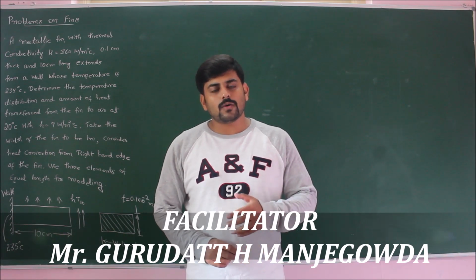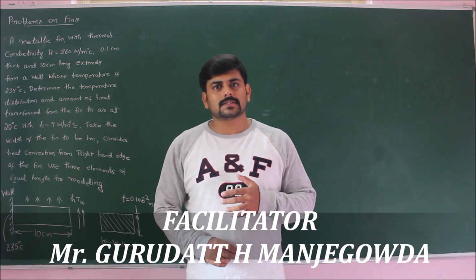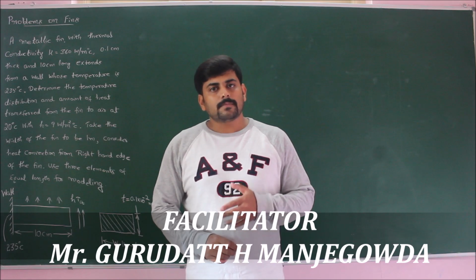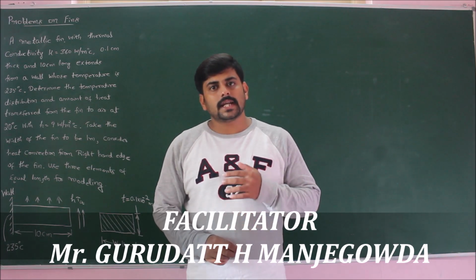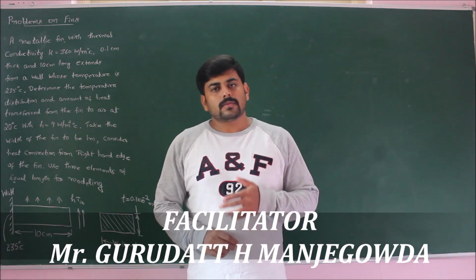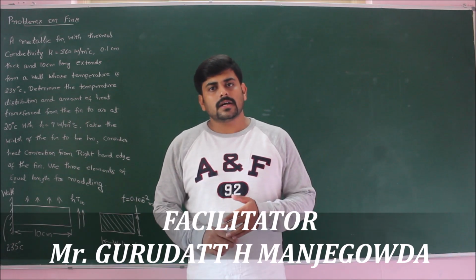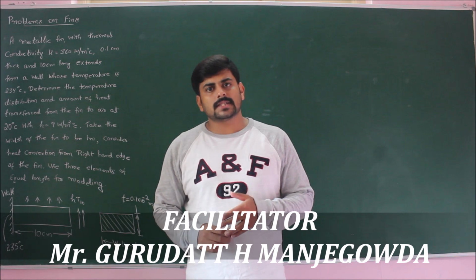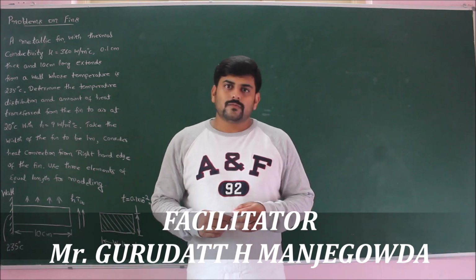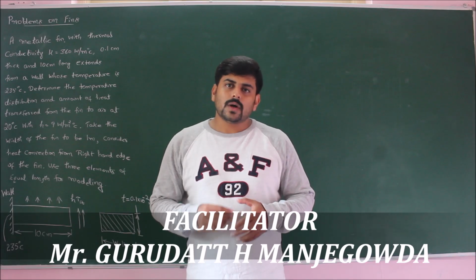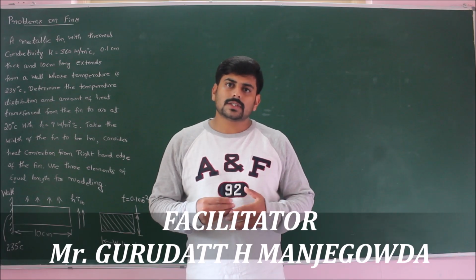In our module 4, we were discussing analysis of heat transfer problems. In our previous lecture, we concluded our discussion on analysis of heat transfer through composite wall. From today's lecture, we will be heading our discussion towards analysis of heat transfer through extended surfaces, which are termed fins. Fins are used in order to enhance the rate of heat loss through convection.